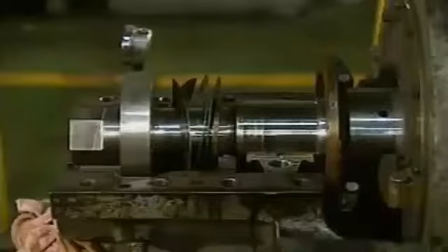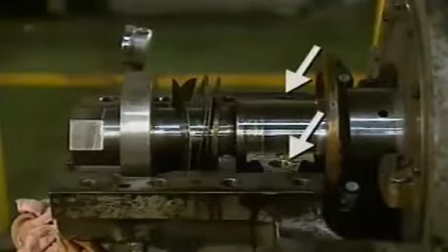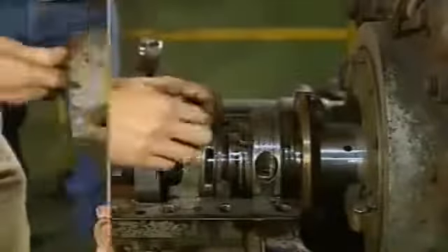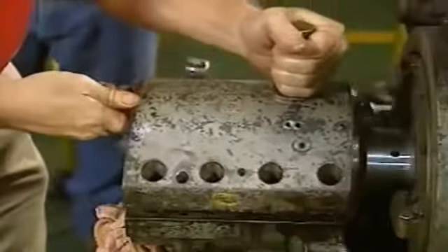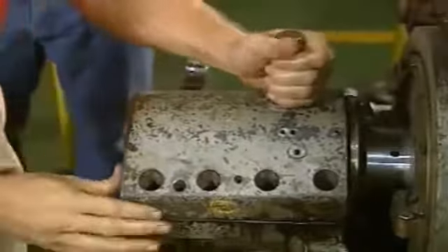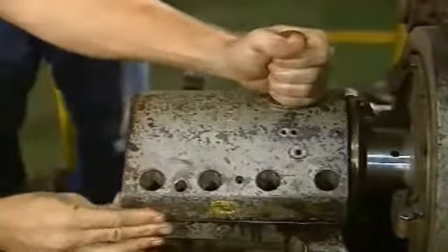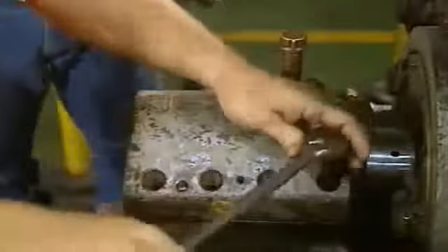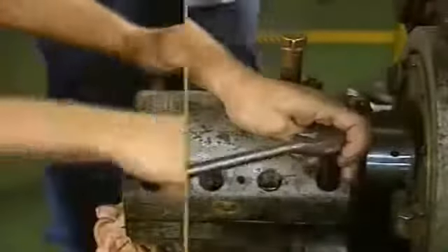After the clearance check is made, the journal bearing is ready for reassembly. The lower shell of the bearing is installed first, and then the mechanic puts the upper shell in place. Once the bearing shells are properly positioned, the mechanic installs the bolts that hold the shells together. Next, the thrust bearings are installed on the shaft. Then the bearing housing is reassembled, and the housing bolts and guide pins that secure and align the housing are installed. Finally, the mechanic tightens the housing bolts, following a pattern specified by the manufacturer to make sure that they are tightened evenly.